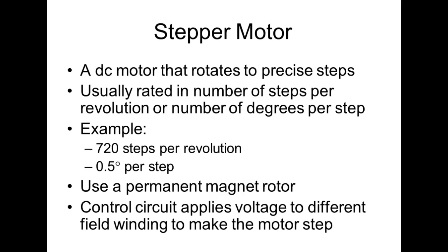But that's done with stepping motors. But what he does is that every time he fires his printer up, he runs it against hard stops. So it's 1,000 steps. A stepping motor don't care if it's stalled, because it's doing it in steps. So if he's got 1,000 steps across there, he does 1,002 steps. The thing would come over here and hit against that hard stop. Now that hard stop would be the zero reference, right? And once he's got a zero reference, if he wants to move it so long, he can transfer that into steps, 2,000 steps. Then move out 2,000 steps. It would be almost perfect.